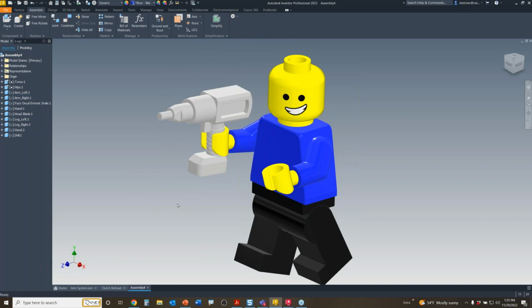So I hope there were a few things in that whole little scenario of different ways to do constraints, all right? Drag and drop for copy paste. This idea of iMates, I hope you see your CAD can be like assembling Legos. You just have to get your library of parts and incorporate those iMates. Those are fantastic things to incorporate, and it can make life so much easier when you do that.